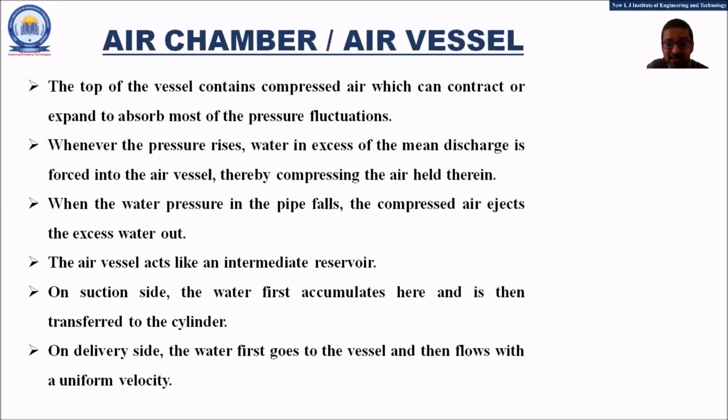On the suction side, the water first accumulates in the air vessel and then it is transferred to the cylinder. On the delivery side, again, the water first goes to the air vessel and then it flows with a uniform velocity to the delivery tank. So friends, these are some of the basic, very fundamental concepts related to the air chamber or air vessel.